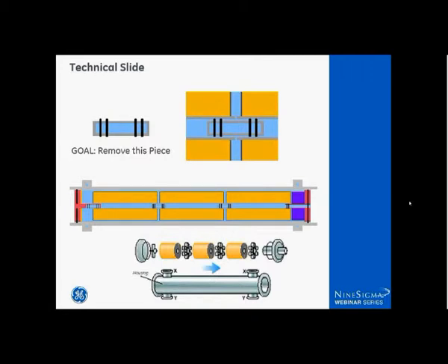So if you look at how we build up a building block for water treatment, we start on the very bottom of this slide with a stainless steel or a fiberglass pressure vessel. And these vessels are anywhere from a meter in length to 6 or 7 meters in length. And that allows us to put as many 40-inch long elements into a single housing as the housing is long.